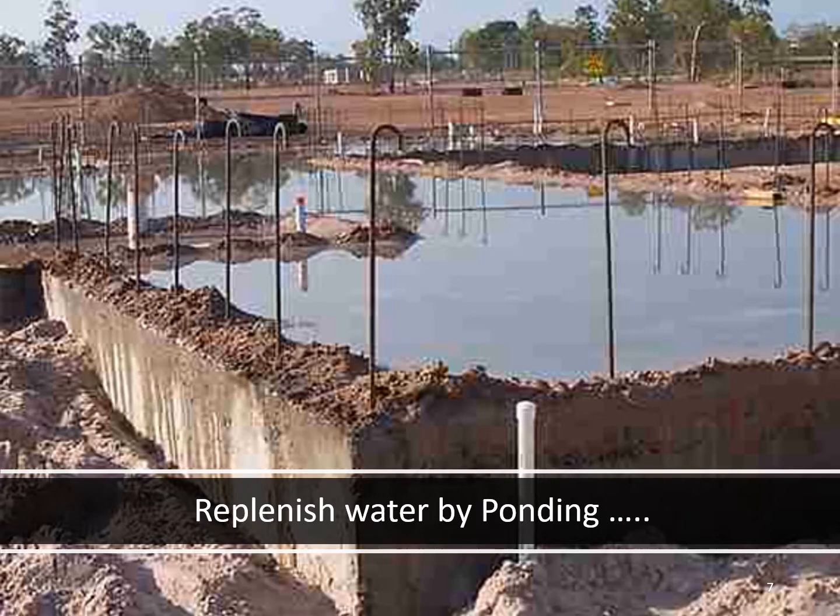Rather than going for the ponding method, you can go for curing by membrane or any other method which is easy and where there is no temperature requirement. In my opinion, if you are not able to maintain the temperature of the water, then it is better to switch to the curing compound, which is the best solution at any point of time.